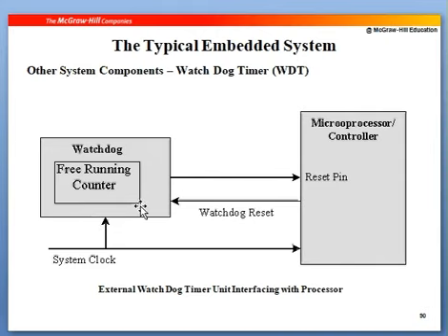You can think of it as waiting for 20 seconds, a count you have to use, and that count will be loaded in this watchdog timer register. That is the count after which you have to produce a reset signal to the reset pin of the microcontroller, and it will be stored in the watchdog timer register.